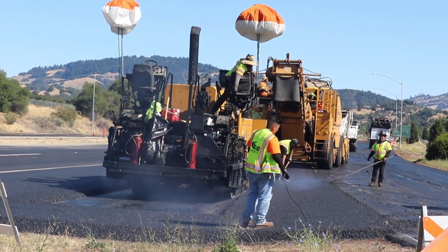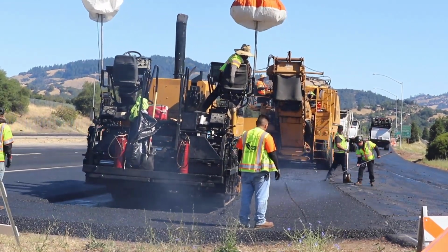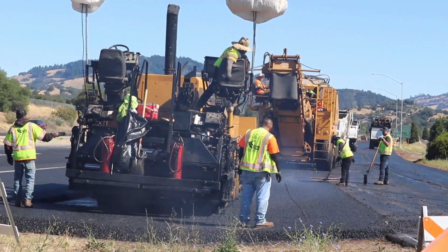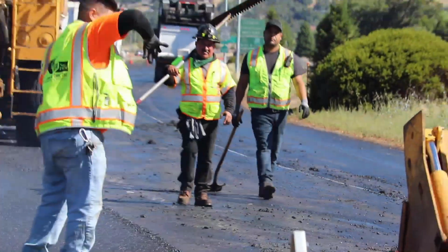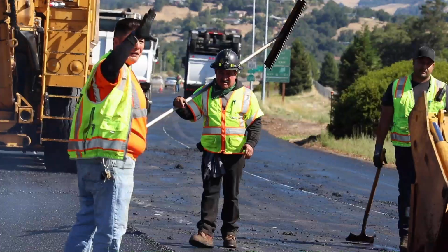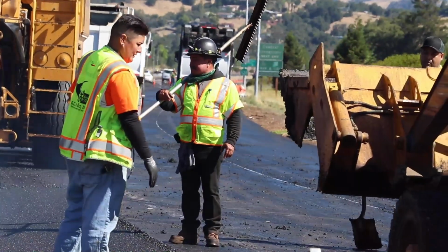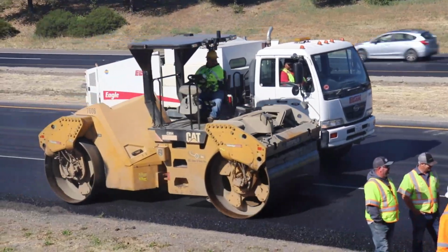Any crack sealing, base repair, and leveling courses should be completed prior to RAC placement with conventional materials and mixes. Please note that crack seal should be down in the crack and not over-banded on the surface. Hot RAC can rejuvenate the crack seal and possibly cause a slip in the mat. Sweeping of pavement and proper RAC coating are critical. Temperature management is essential to successful RAC mix placement and compaction.